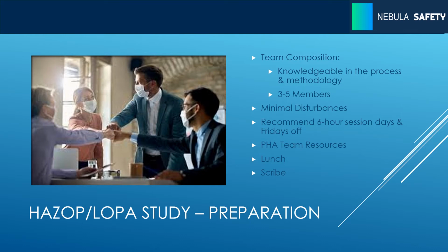Typically, we like to keep the PHAs around a 6-hour session. And of course, that's not including breaks and lunch and stuff like that. Just in my experience, I've found that 6 hours is a good time to keep the team focused. I, of course, have worked longer PHAs because, once again, the facility does not necessarily want to lose their personnel for multiple days, but I have noticed that the team quality does start to degrade after 8 or 9 hours. You just get tired. The brainstorming is no longer quite off the top of their heads. It's more just trying to say whatever they can to kind of close out the day.